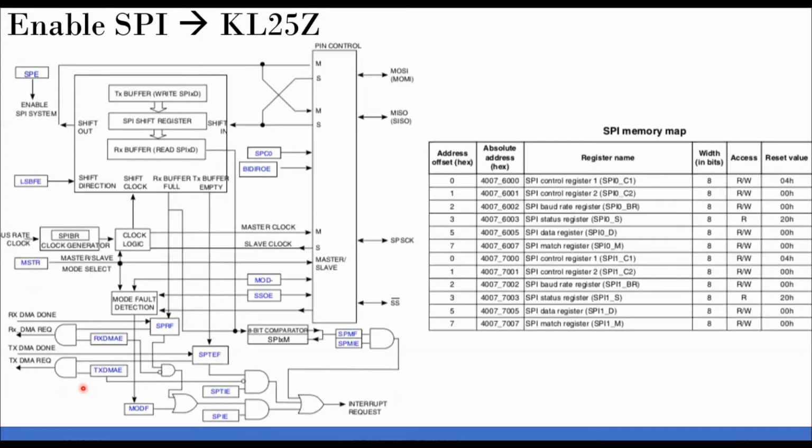So we'll have a small discussion on DMA. It is an advanced concept. So DMA is something like, conventionally, how does the communication happen? The slave or some sensor will put the data into your register, for example, in this RX buffer, and then you use the load command to read from this register. So everything is going through the CPU, right? You load from the sensor to the memory, and then from memory you do something. So you want to avoid that. You want the peripherals to have some access to the memory, not necessarily through the CPU. So there is a possibility, and that is known as direct memory access. So peripheral to peripheral communication through memory without the help of a CPU.